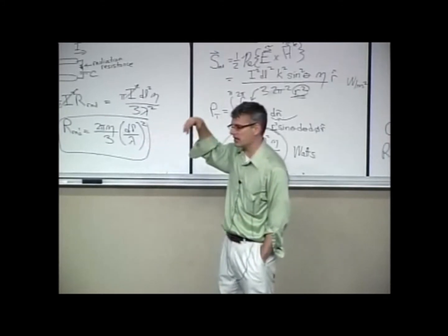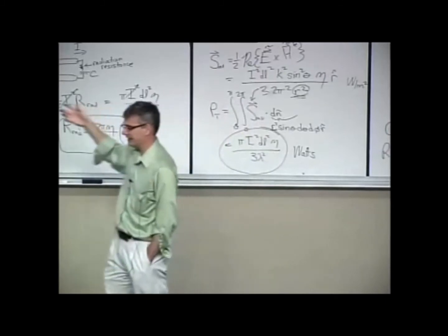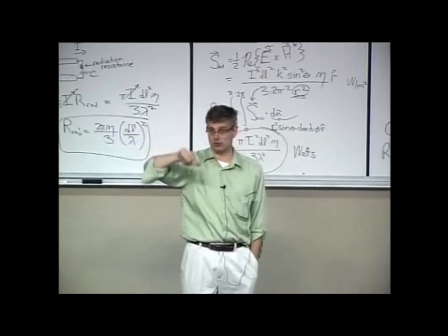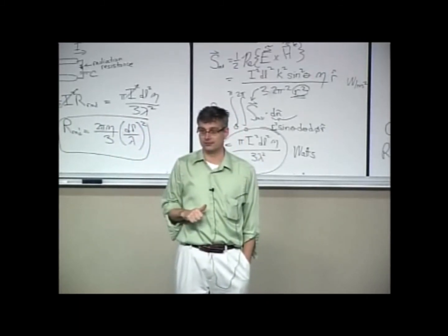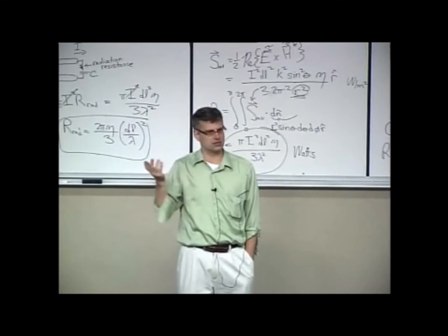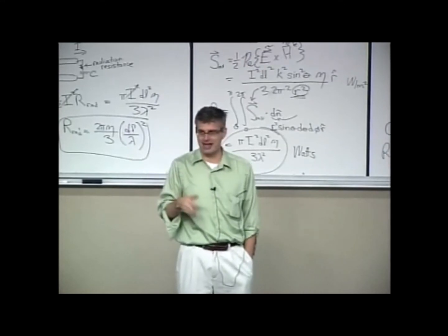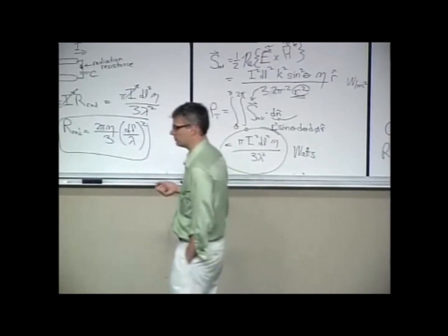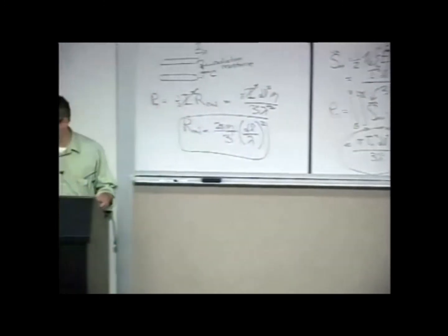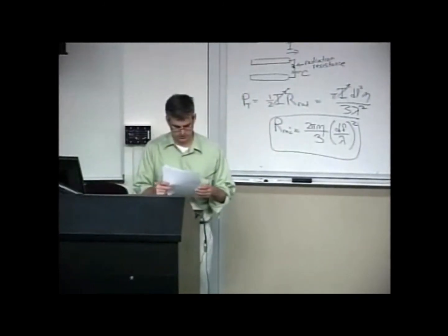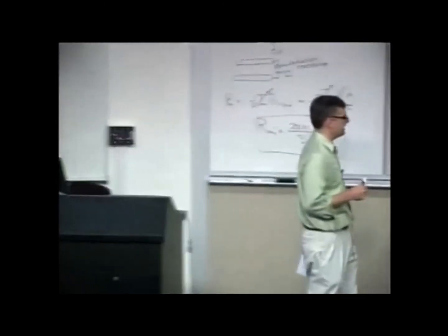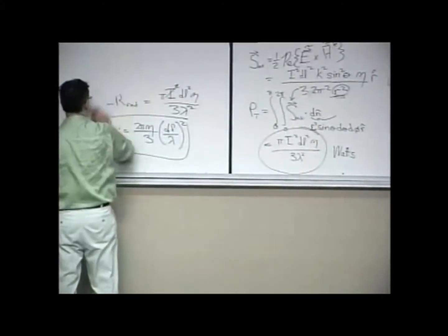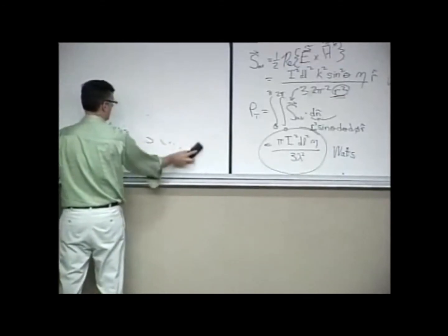So we've defined a couple of key parameters in antennas. We've talked about the directivity. We've talked about its relationship to gain, which is what we use in our link budget equation. We also talked about impedance, just because it's good to know that parameter to make sure that you're matched with whatever transmission line you're feeding it. And there are a couple other things that you should probably know about antennas. Once you've calculated the directivity, or the gain, there's a nice parameter that we often see on spec sheets called the half-power beam width.